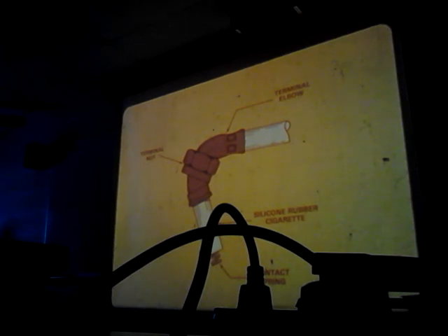The end of the conductor usually has a spring that presses against the inside of the central electrode of the spark plug. And a silicone rubber cigarette about 1 inch long insulates the high voltage from the steel shell. The end of the shielding is then attached to the terminal elbow. When the lead is inserted onto the spark plug and the terminal nut tightened, there is a continuous metal shield around the spark plug and lead, all the way to the magneto.